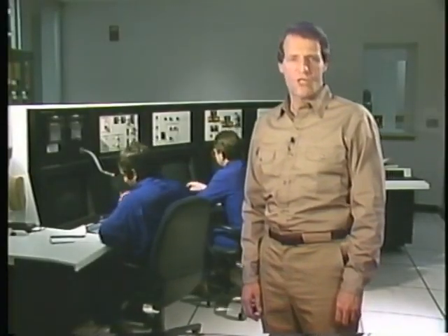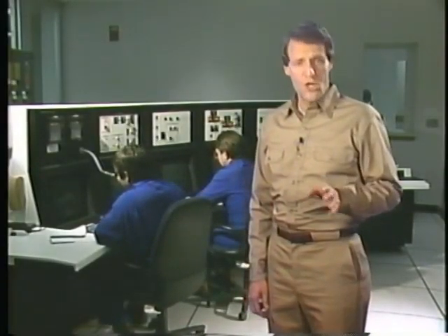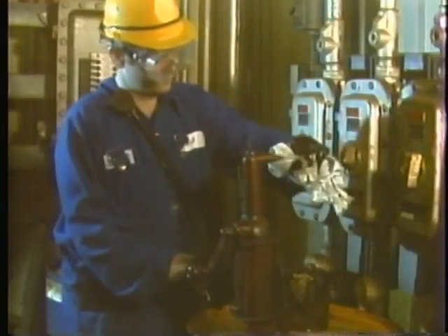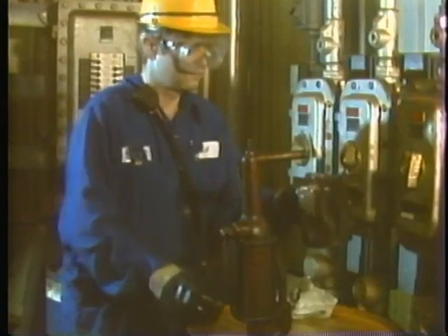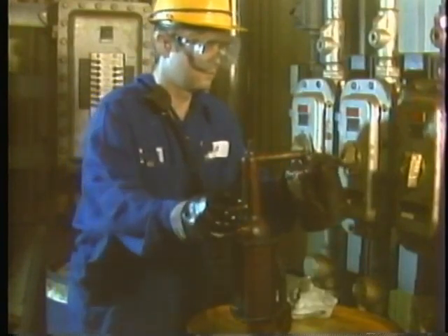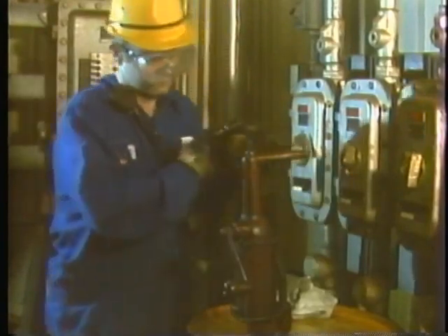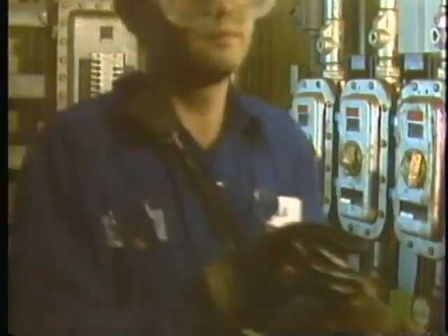In the example we just saw, the fluid level could be checked through a sight glass, but in some cases a dipstick may be used. If fluid has to be added to the reservoir, the operator has to make sure he uses hydraulic fluids that have the proper viscosity and additives, since fluids without them can cause overheating or damage system parts. To reduce the chances of fluid contamination, only a clean container or hose should be used to transfer the fluid from storage to the reservoir.